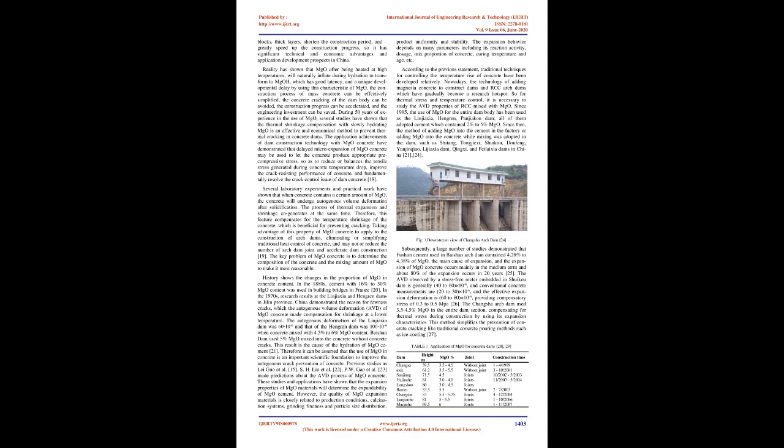During 50 years of experience in the use of MgO, several studies have shown that the thermal shrinkage compensation with slowly hydrating MgO is an effective and economical method to prevent thermal cracking in concrete dams.